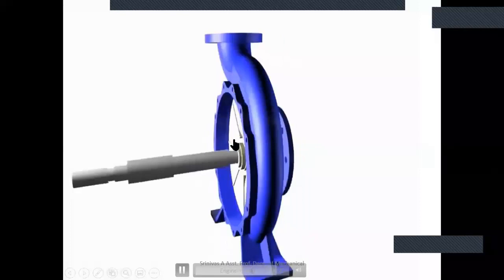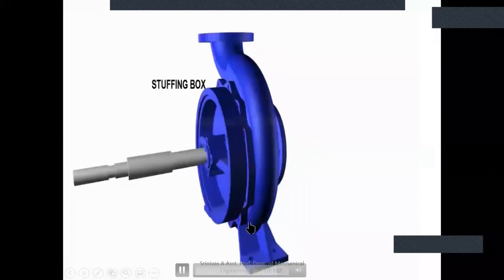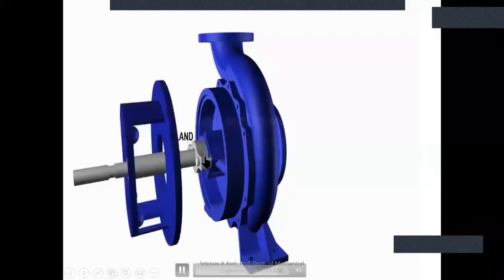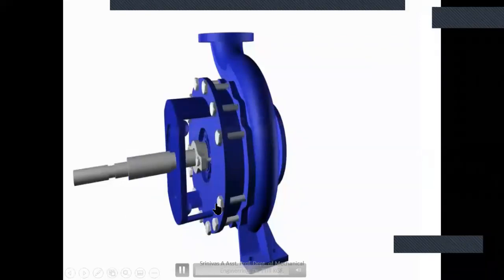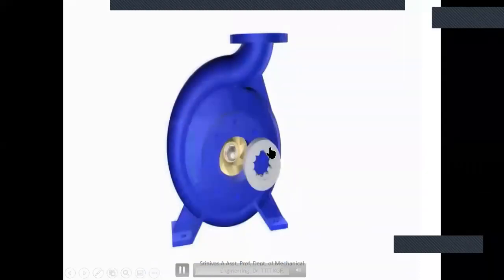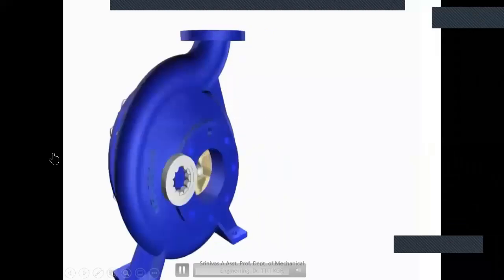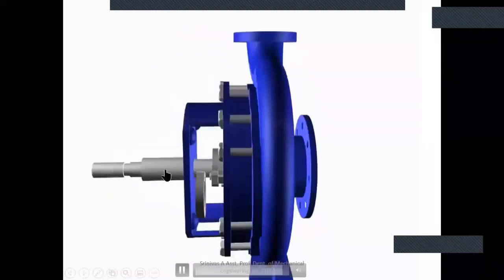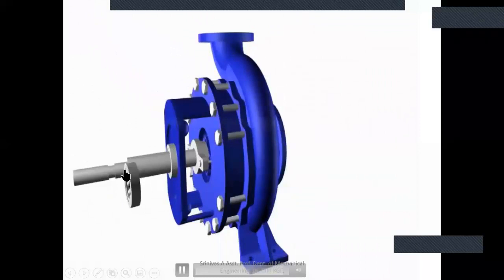And you can see just this one, my full arrangement. For the casing, a stuffing box is connected and a suitable gland is connected over here, then a supporting structure is made here, and then bearings. Mainly for the shaft, two sets of bearings are added. The function of bearings, we know, is to give rigid support to the shaft and ensure smooth running of the shaft. Then the gearbox is attached to this, and this is the complete structure of a centrifugal pump.